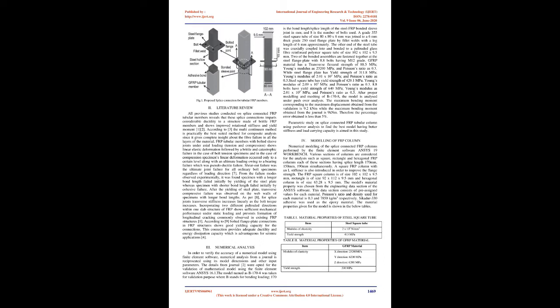[1] Based on further studies on connecting steel tubular members, a splice connection is developed for connecting tubular fiber reinforced polymer, FRP, members, Fig. 1, and this steel FRP connection system consists of two components, a bonded sleeve joint, BSJ, coupling FRP and steel tubes adhesively, and a bolted flange joint, BFJ, connecting two steel hollow sections through fillet weld. The BSJ reduces stress concentration in the FRP compared to bolt fastening, while the BFJ enables convenient installation and imparts ductility to the system, through steel yielding.